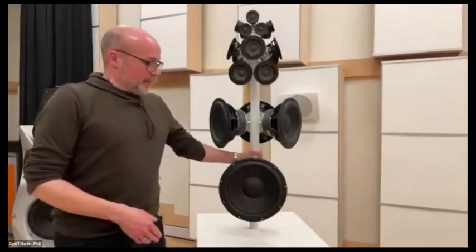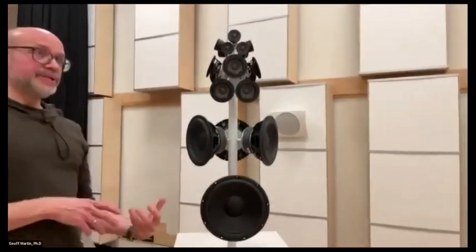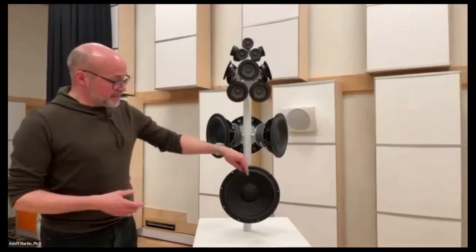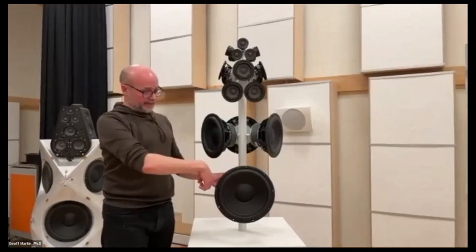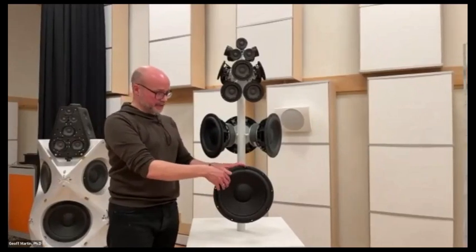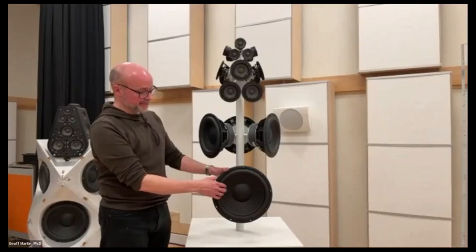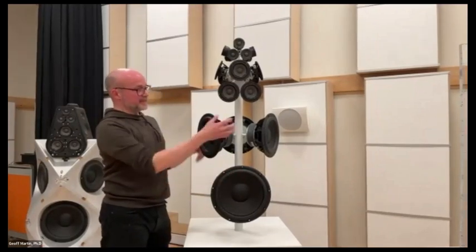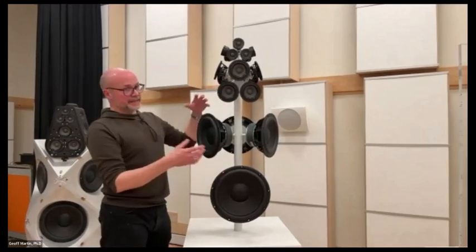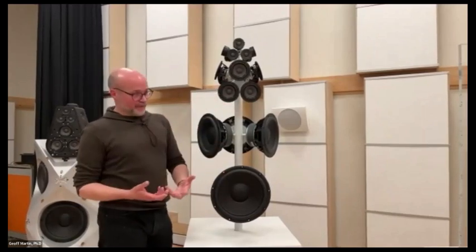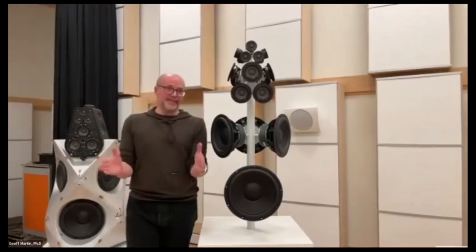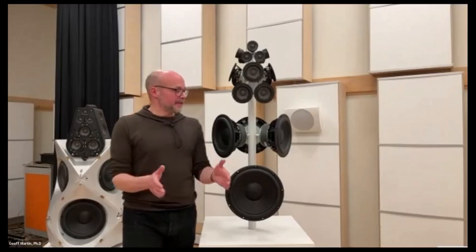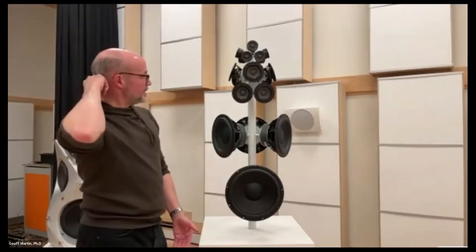This is the result of our acoustical engineers and our DSP engineers calculating, based on the horizontal radiation patterns of these drivers individually in their boxes, where these drivers needed to be in space to give us the beam forming capabilities that we wanted: a beam that was as narrow as possible and as same as possible at as wide a frequency range as we could do.